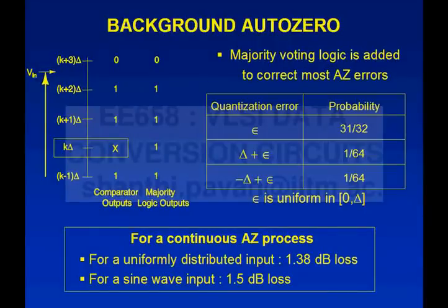Unfortunately, while that sounds very nice, in practice please note that the substitute must substitute for comparator 1 for some time, it must substitute for comparator 2 for some time, etc., all the way up to 63. This is a 6-bit flash converter.